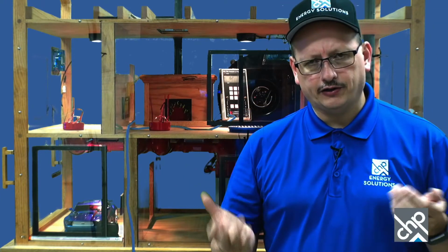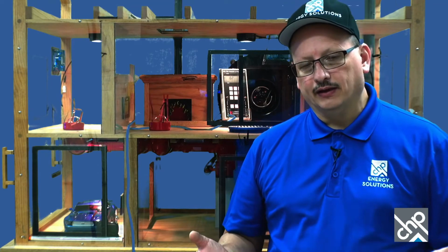So when you turn on your air conditioning or your heat, even though that door's closed, it's acting like it's not there if you've got very little to no pressure across that door. So right now you may have a lot if there's not much undercut, or maybe you've got too much air coming into that room. If you have a high region, you might have a high number.